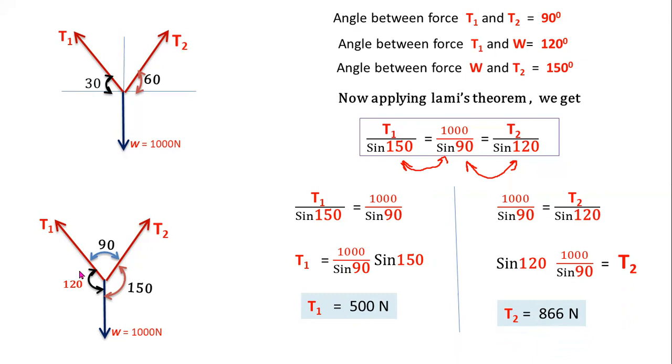First, you have to convert the given diagram into a forces diagram. After that, you have to convert that forces diagram into a free body diagram. After that, you have to apply Lami's theorem for determining the unknown forces in the strings. In the next class, I will explain more problems on this concept.